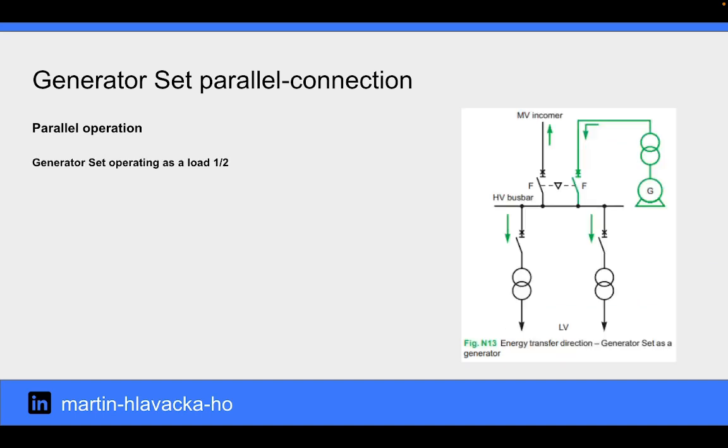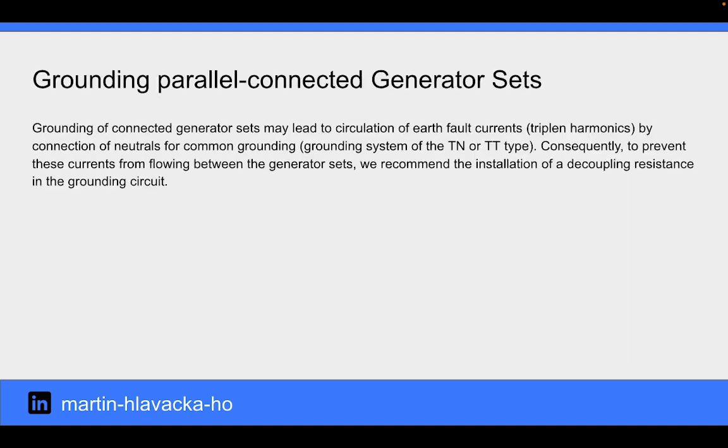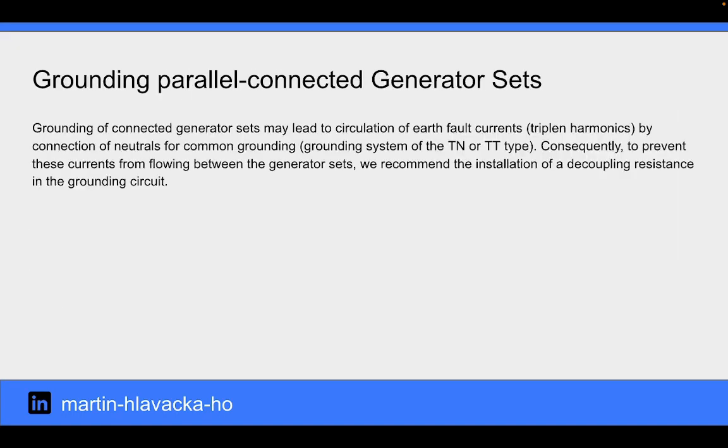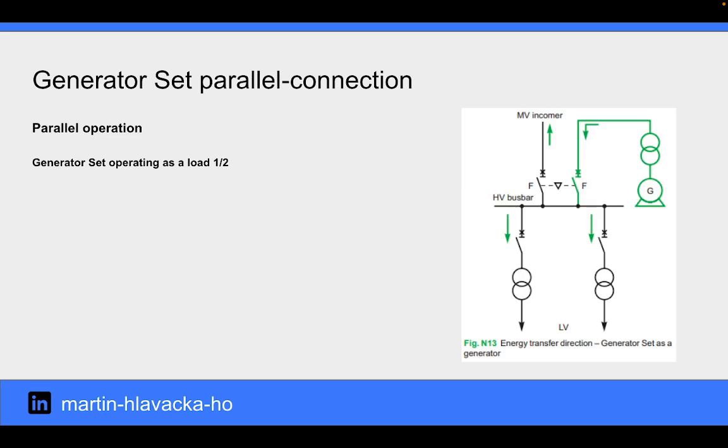Generator set operating as a load. One of the parallel connected generator sets may no longer operate as a generator, but as a motor.